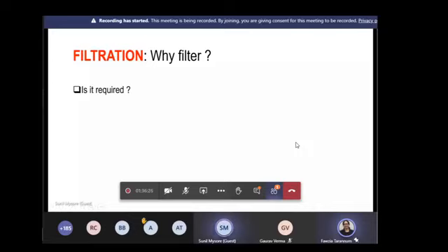So it says, can we avoid manual intervention here? How can we make it completely hands-free? You can use a solenoid-based valve if you want. You can put a PLC there and control that. That is possible. Automatic valves are available. You can also use a centrifugal filter instead of all this filtration. It's available off the counter. You can just go buy that filter which comes with the flush-out valve, which actually works automatically.